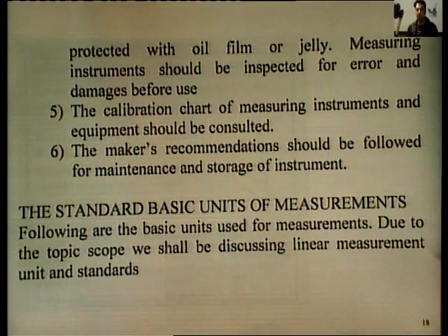If the micrometer measures from 0 to 25 mm, a small cylindrical stick is given which has a length of exactly 25 mm. So when we take a reading of this 25 mm stick in the micrometer, we come to know whether the condition of the instrument is all right or not. And accordingly, we may make some changes in the readings which we are taking.